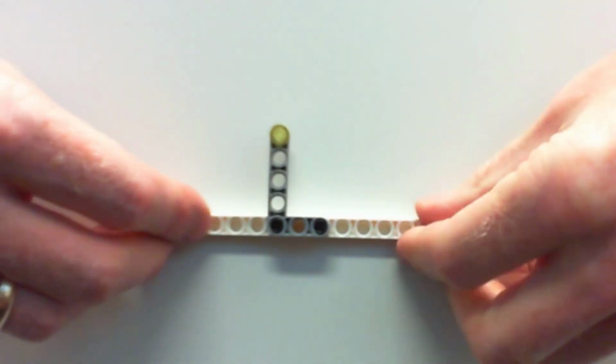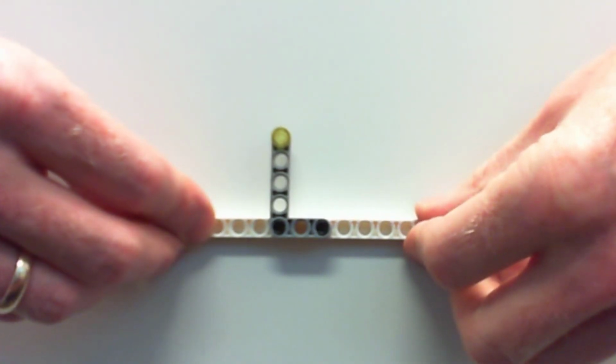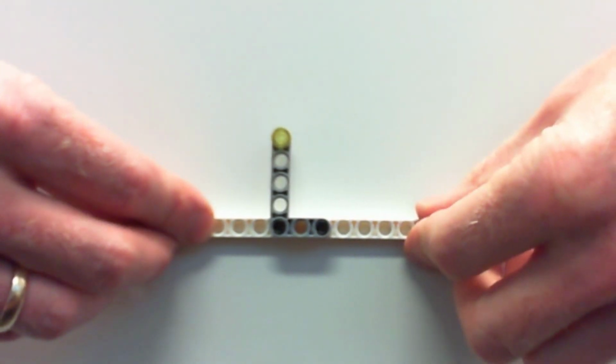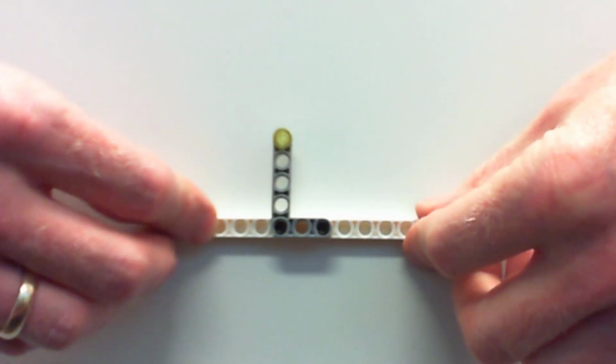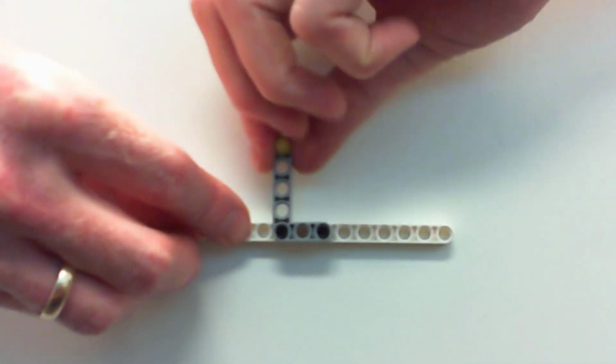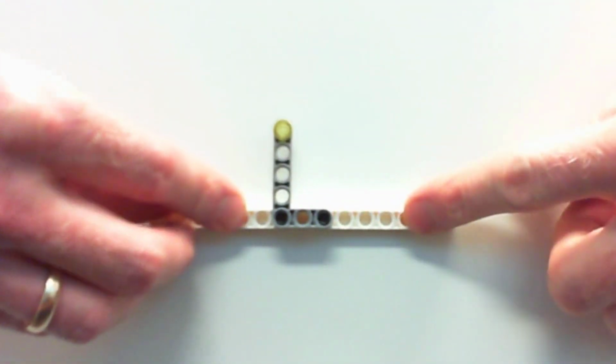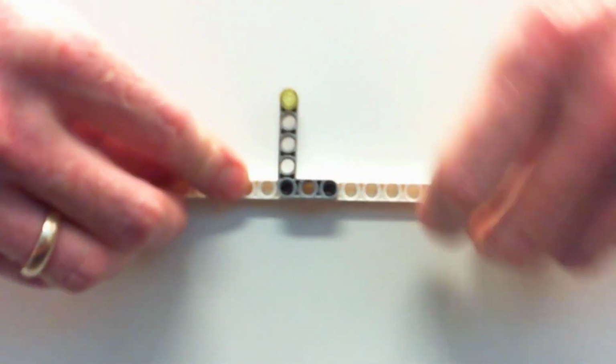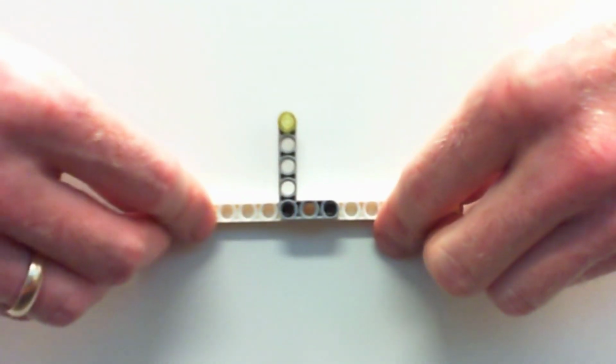And so the final reaction we have is fixed. Okay, so if you weld something to something else, if you bury something in the ground, you essentially pick up three different reactions. Okay, so this one is fixed to the white surface, and so I can't rotate it, for one. Okay, so it has a resistance to rotation, basically a couple coming from that connection.